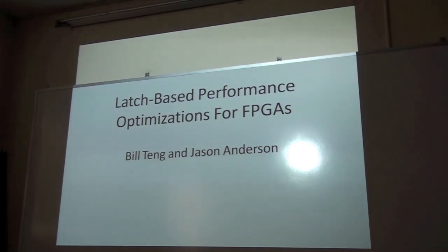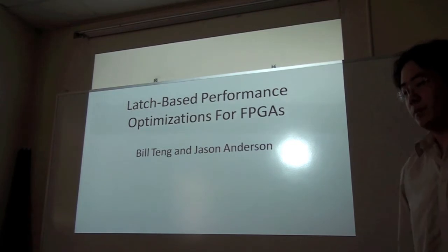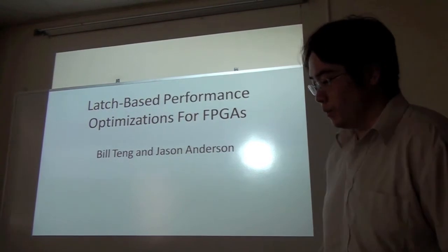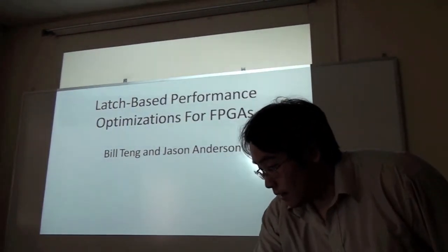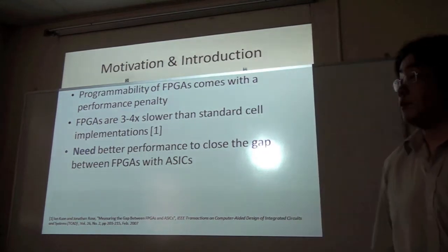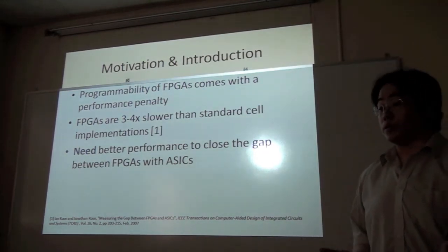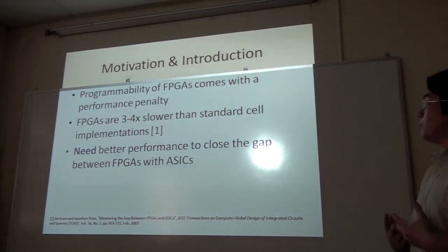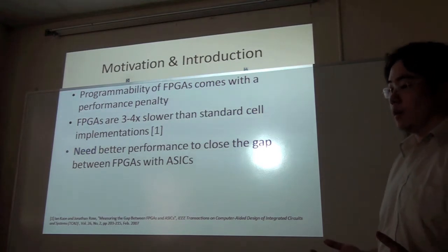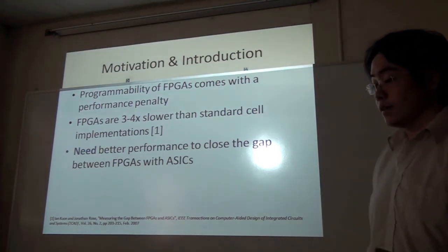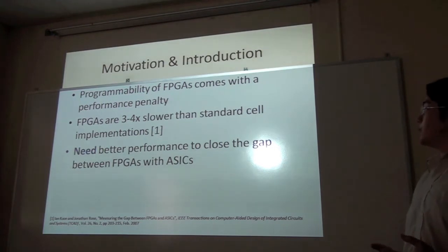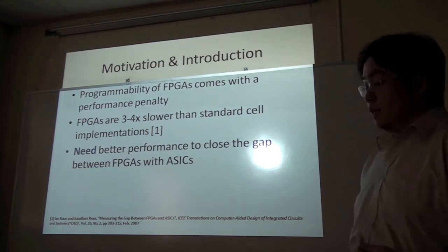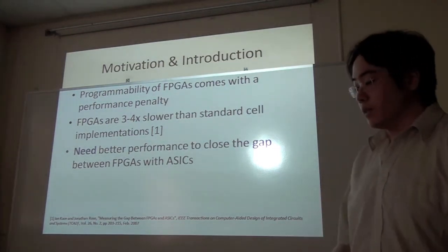Yep, thank you, Paul. Today I'll be talking about latch-based performance optimization for FPGAs. Jason and I submitted this to FPL, and hopefully we'll be hearing from them soon. So the first question we have is, why do you want to use latches? The reason is that the reprogrammability of FPGAs has a performance penalty. In fact, it's around 3 to 4x slower based on a study done here at the U of T by Dr. Kwan. So we need to somehow close this gap between ASICs and FPGAs.